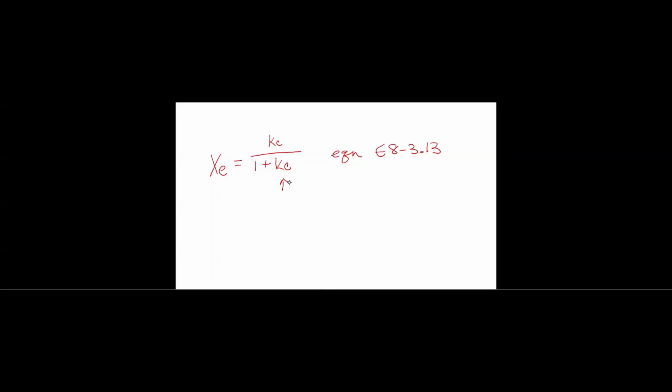I used Polymath. That's what I would recommend using. So here is my Polymath example code. You'll see up top here are our differential equations that we defined previously. Nothing fancy with those, just the equations as discussed from the book. After that are the explicit equations. These are the equations that we defined for other variables. So Kc with respect to temperature, K as a function of temperature, the rate of reaction with respect to A and its definition, as well as the equilibrium conversion are there.